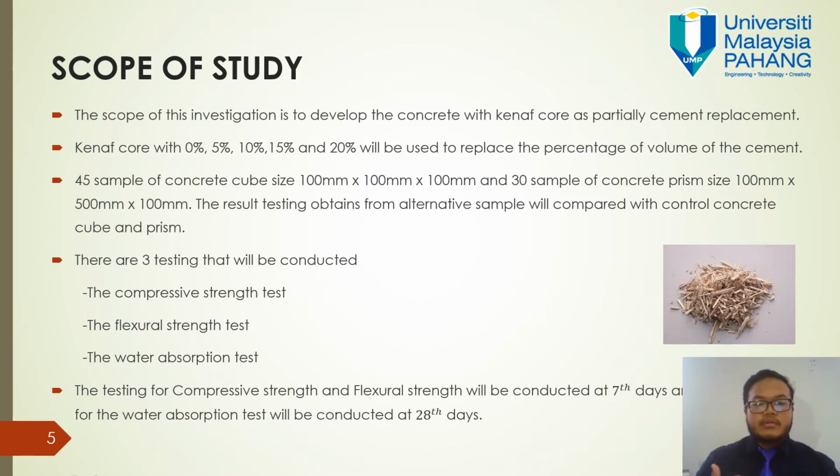Kenaf core at 0, 5, 10, 15 and 20% will be used to replace the percentage of volume of the cement. 45 samples of concrete cube, size 100 times 100 times 100 mm, and 30 samples of concrete prism, size 100 times 500 times 100 mm, will be prepared. The results obtained from the alternative samples will be compared with the control concrete cube and prism. There are three tests that will be conducted: the compressive strength test, the flexural strength test, and the water absorption test. The compressive and flexural strength tests will be conducted at 7 and 28 days, while the water absorption test will be conducted at 28 days.